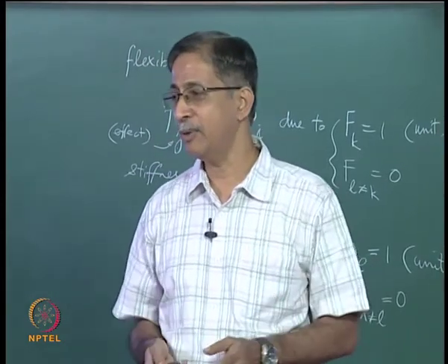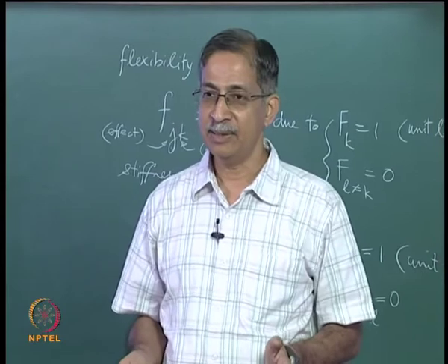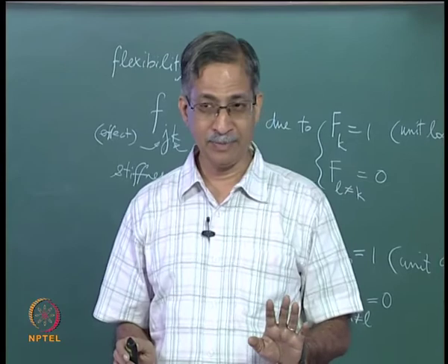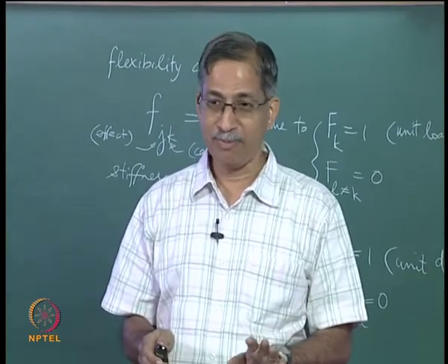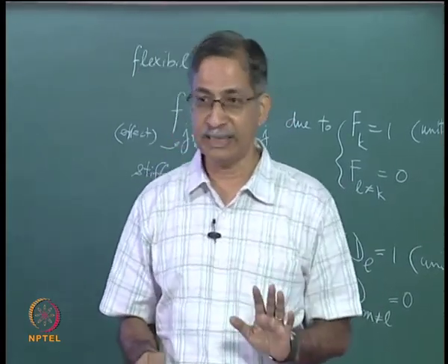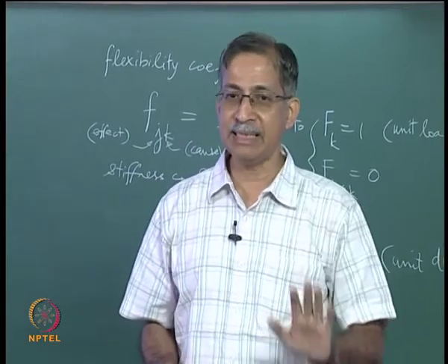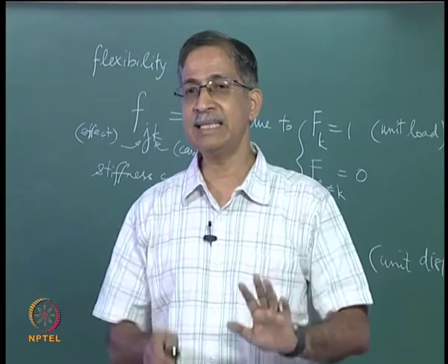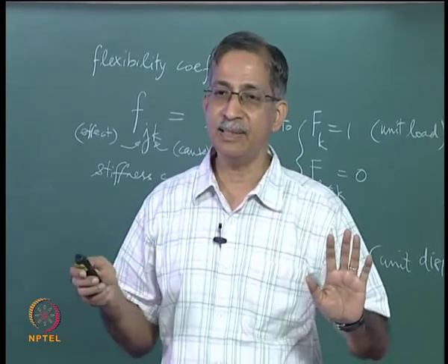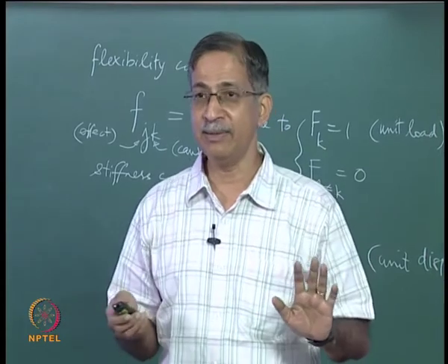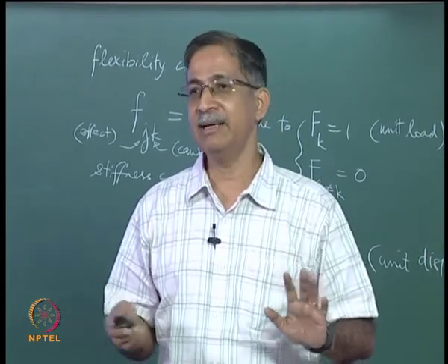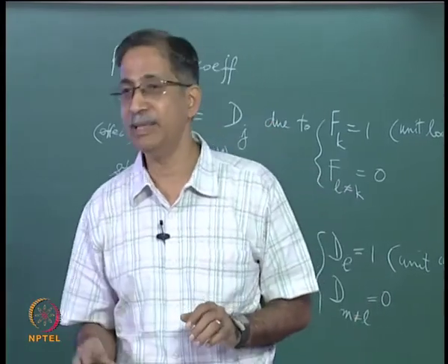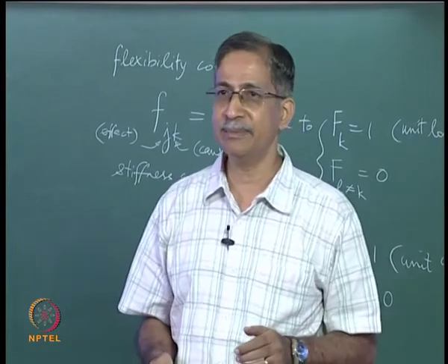So simple. So you have two kinds of applications, one where it is a pure geometry problem, there are no forces involved. Second, you might tend to get confused, there are forces involved, but those forces, you are looking not at the force field, you are looking at the displacement field. It is still a geometry problem, an unsolved geometry problem, but you get some parts of that displacement field. For example, here the rotations, the curvatures, and there are some parts which you do not know, like the joint displacements, and to find the unknown joint displacement you are invoking the principle of virtual work.